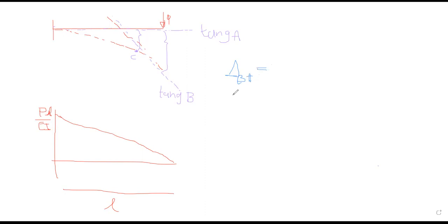So the moment between, so we took the area in the previous case, PL squared over 2EI, okay? This was the area, and be careful then how to take the moment of this area. You should consider it from the first letter. You should take moment from B. So the distance to the centroid is how much? 2L over 3, right?